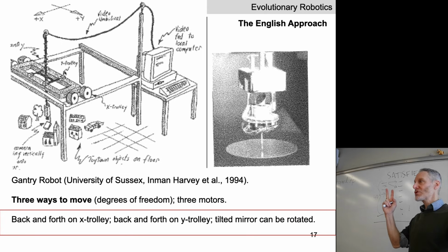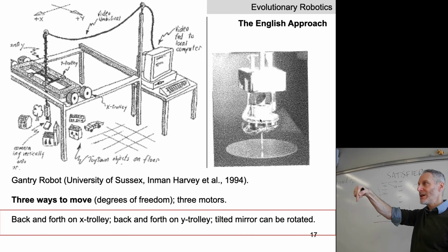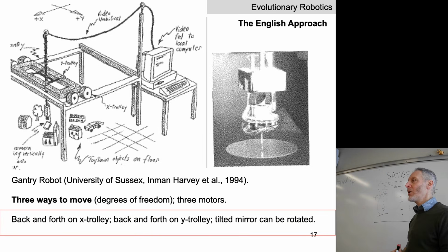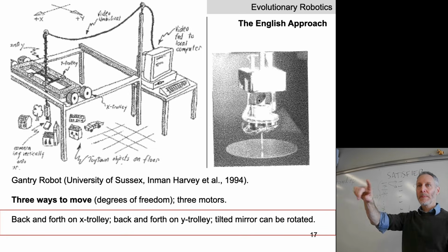Motor 2 drives the Y trolley, and motor 3 is always on, and it just rotates the dental mirror to give the downward pointing camera a 360-degree view horizontally around the robot. You'll notice that the dental mirror is angled at 45 degrees, right? So this 45-degree mirror is spinning. It's basically an upside-down periscope. Okay, all right, so hold on to that.